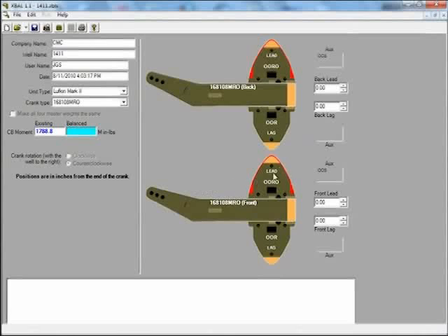In this case, I already put the data in for this well, which has a Lufkin Mark II 168 with 108 MRO cranks with these counterweights. They're all at the end. These two weights have auxiliary weights. That's what the red outline indicates. And the maximum counterbalance moment for the existing counterweight configuration is 1788.8 thousand inch-pounds.